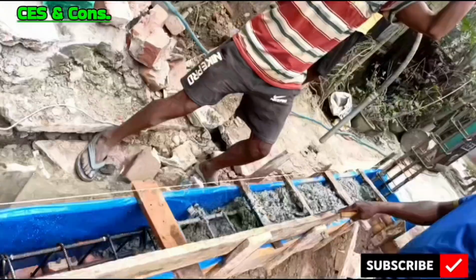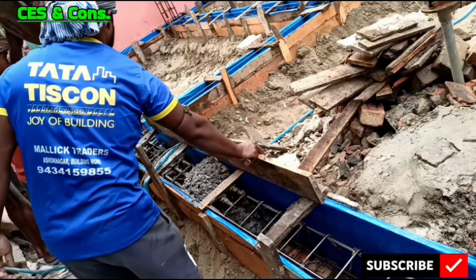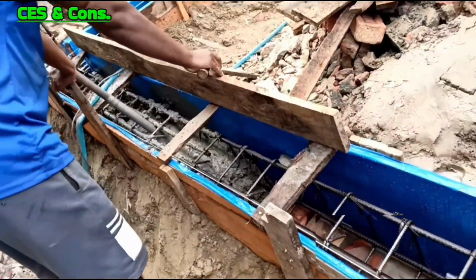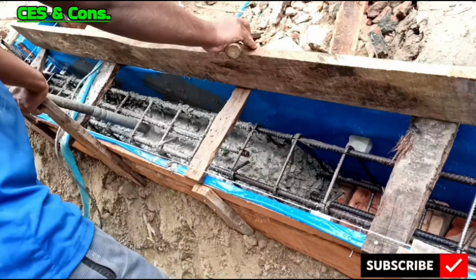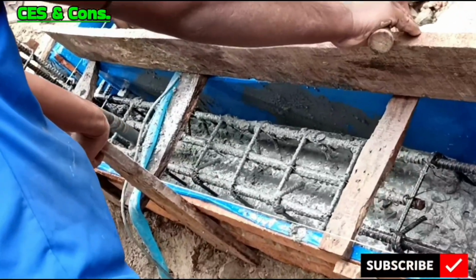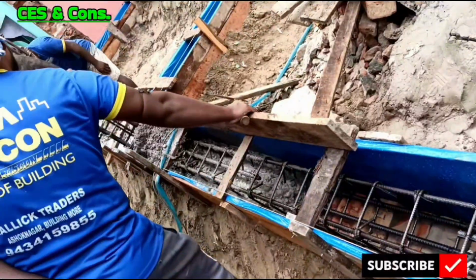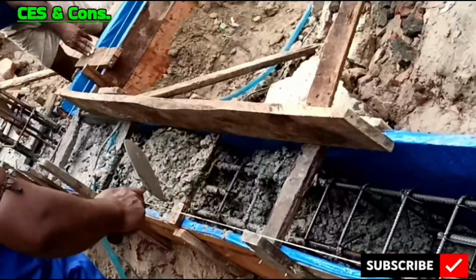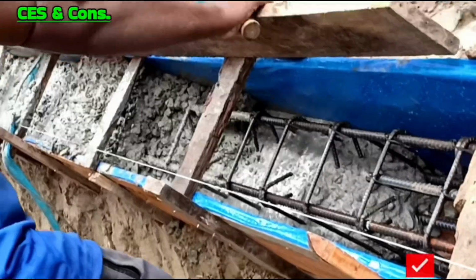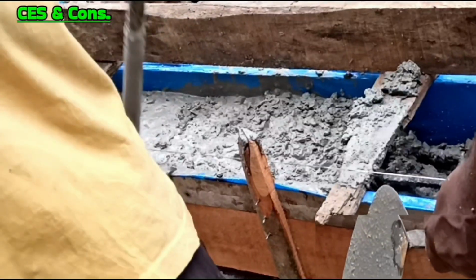Now I am going to the development length of the bar. Friends, I hope that you have already seen here that all the longitudinal bars of top and bottom of the beam are extended at the end in the form of an L. It is the required development length of that bar. For accurate prediction of development length, you may please refer to clause number 26.2.1 of Indian Standard Code 456/2000.